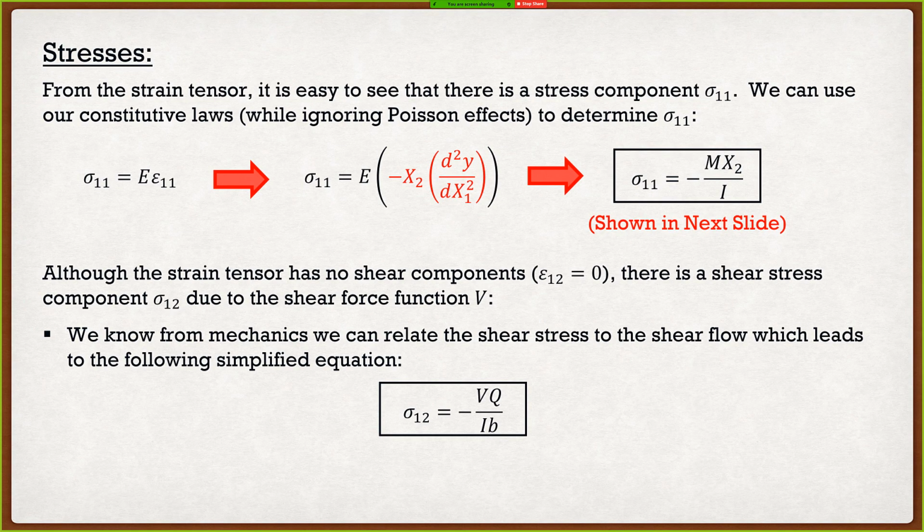So if we were to look at that, shear, no problem. Moment of inertia, no problem. B, no problem. What about Q? Q is the only real tricky part. However, since we aligned our axis with the centroidal axis of the beam, we can easily find Q by taking the following double integral, and we get that Q is equal to B times T over 2, where T is the height of the beam, or the thickness of the beam, divided by 2, minus x2 multiplied by T over 4 times x2 divided by 2.